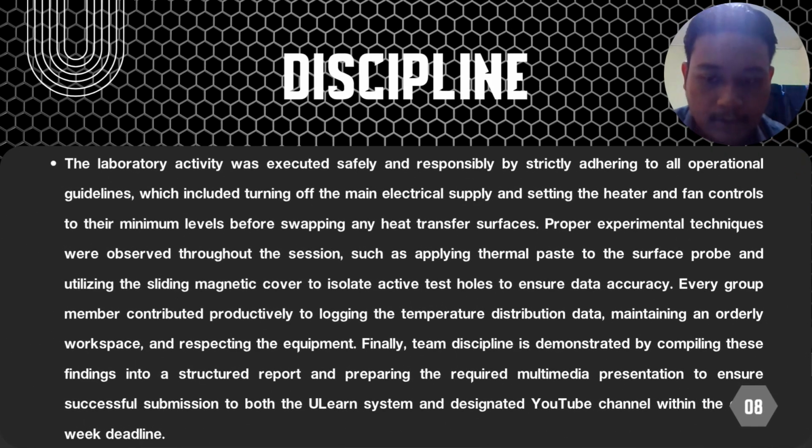Okay, next is discipline. Strict adherence to operational guidelines ensured the safe and responsible execution of the laboratory activity. Prior to swapping any heat transfer surfaces, the main electrical supply was deactivated and both heater and fan controls were adjusted to their minimum thresholds.